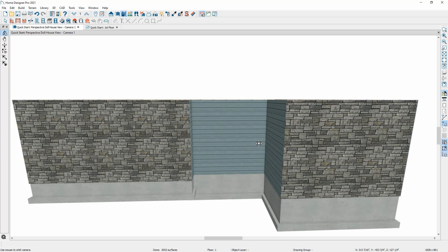And there's several ways you can add doors into the plan. You can go up into your door tools, and there's just a straight hinge door, a doorway, a sliding door, pocket doors, bifold doors, and so forth. I'm just going to select our straight hinge door and then come into the plan, and as I move my mouse over this wall, you'll notice that I get a little gray outline indicating where it's going to be placed.